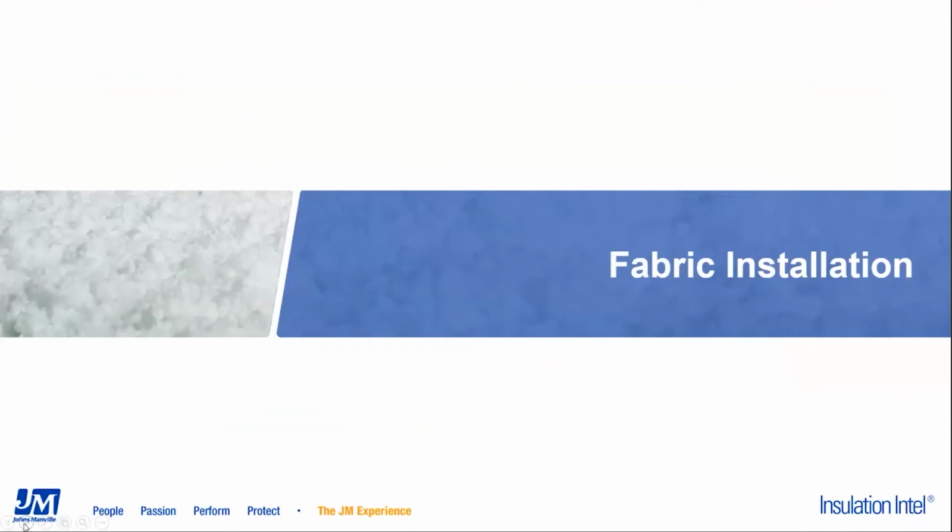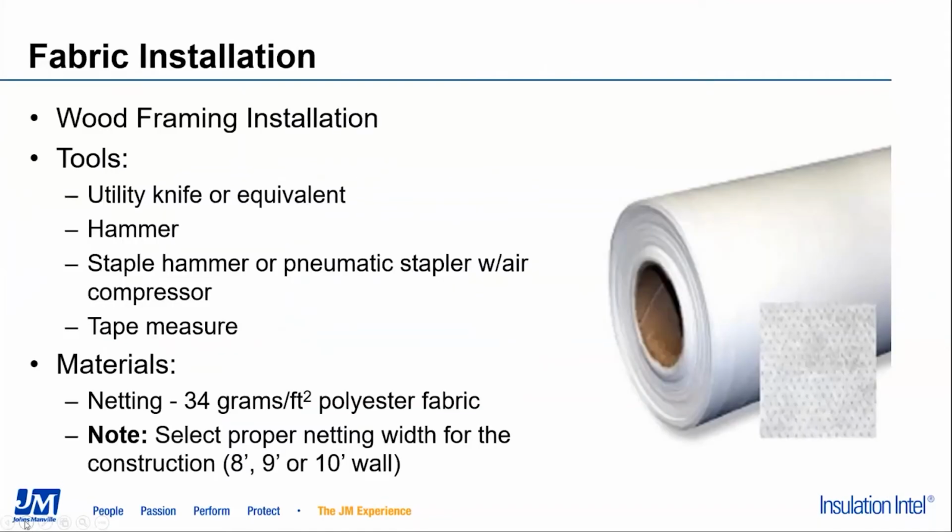So, fabric installation is one of the most important parts of the entire process. Poorly installed fabric will lead to a host of problems once we start to fill all of the cavities. Some of the tools that we're going to need for this fabric installation would be a utility knife, hammer, staple hammer, compressor if running a pneumatic stapler, tape measure, and of course our netting. Make sure that we are selecting the proper size netting for the wall, whether that be an 8, 9, or 10-foot wall.